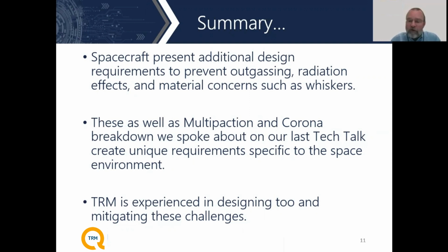So why is outgassing so important on a spacecraft? Well, if material is leaving a device and those collected volatiles are going to resettle someplace else on the satellite, the last place that you want to have dust settling is on the lens of your very expensive camera or other sensor that you have on the satellite.